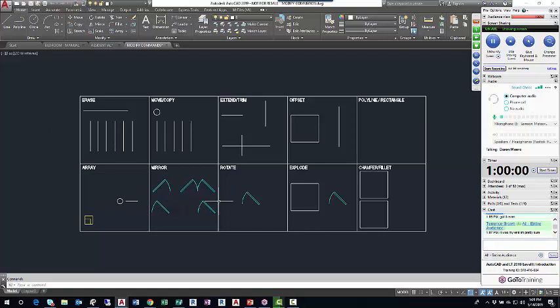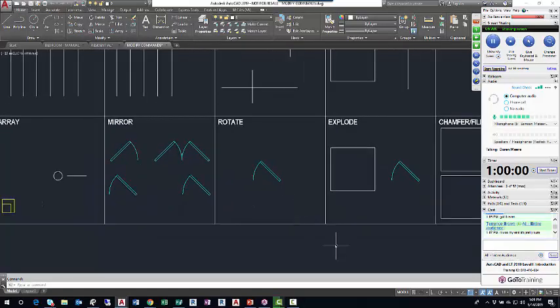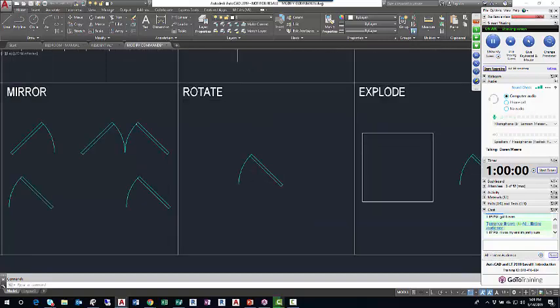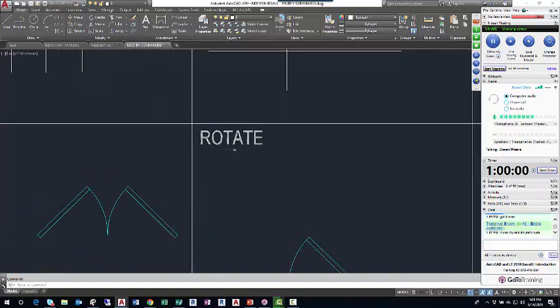The rotate command is one that we'll use when we start to bring in our doors, there's actually a rotate built into the insert command when we insert the doors. But if you need to rotate something just because you need to, like sometimes you need to rotate text. If I want to rotate this text so it stands upright, I'll select my text, I'll select the rotate button, left click rotate, and again habitually moving the crosshairs into the drawing window to get the prompt. The prompt is just like the prompt with move, specify base point, and copy.